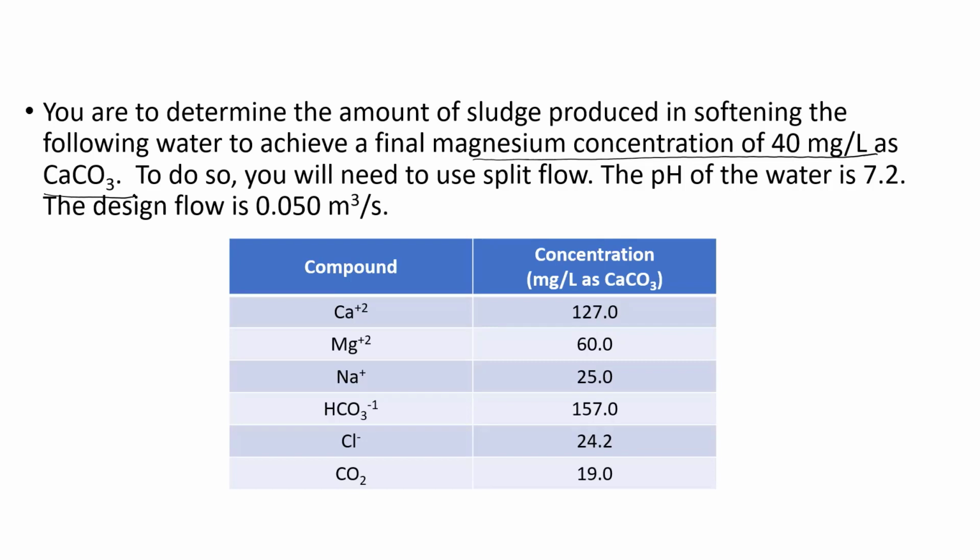So typically we use that as a criteria, and that's because while both calcium and magnesium are the major contributors to hardness, magnesium is more costly to remove. It produces more sludge, and at concentrations greater than 40 milligrams per liter, the magnesium tends to precipitate out and coat the surfaces of heating elements.